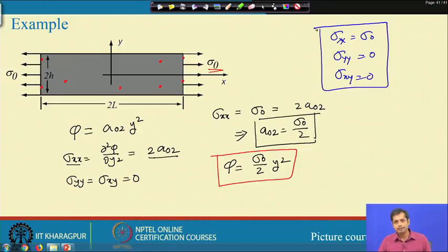Now, once we have stress, next we have to determine the strain, and for that we have to bring in the constitutive relation, the relation between stress and strain. For any material, with the same state of stress, same boundary conditions, same geometry, every time you will get the same stress distribution. But when we convert stress to strain and then strain to displacement, material property will come in. Let us find out how to determine strain using the stress strain relation.